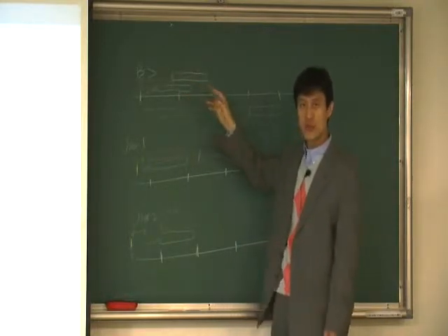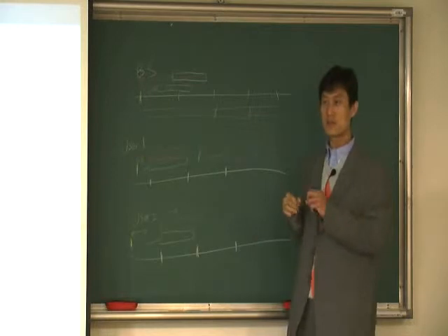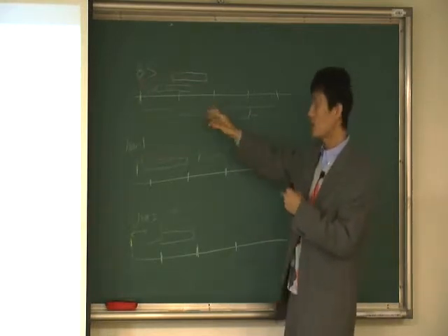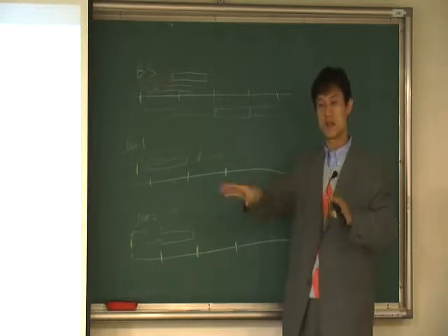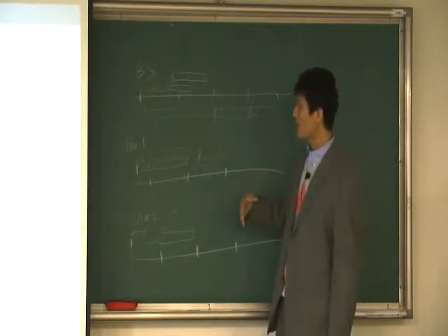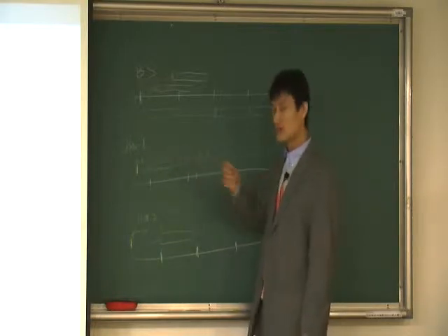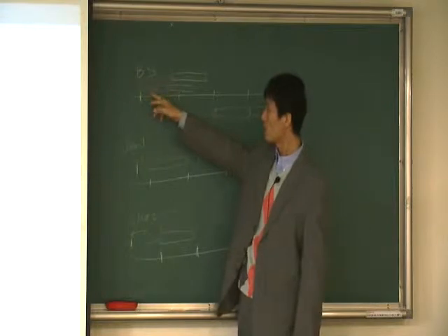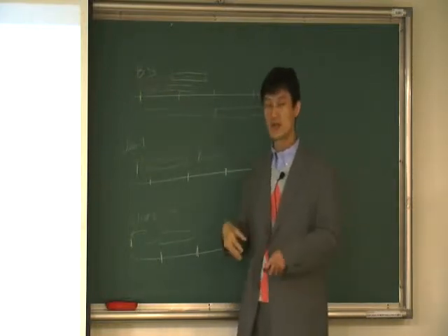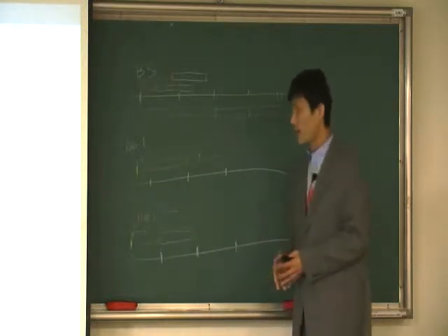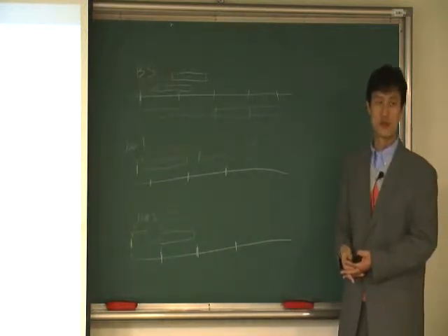First thing is that you have to transmit random access. Downlink synchronization is always easy, okay? Because the base station always transmits the synchronization packet. But uplink, it's not the case. So first thing to do is you have to do random access, and then based on this round trip time, user 2 will synchronize uplink timing. So this is where the random access is used.